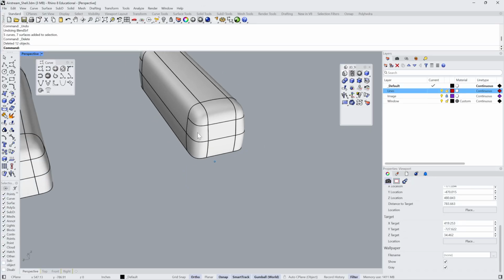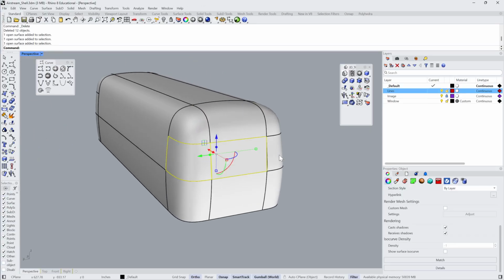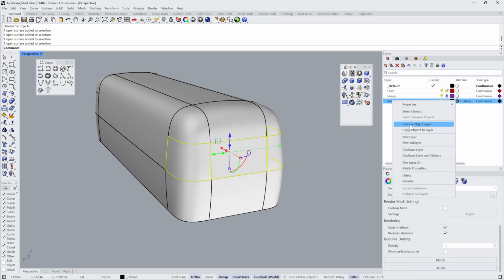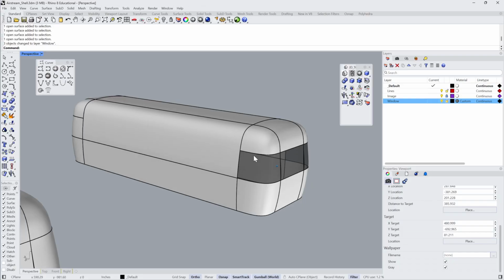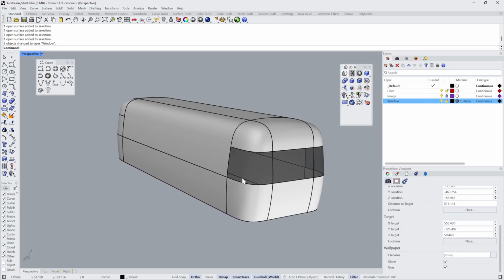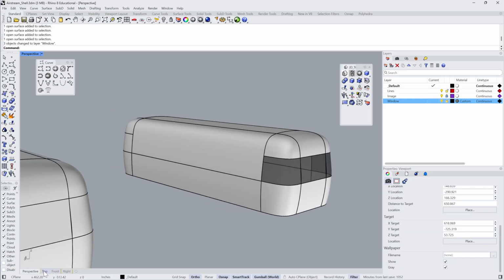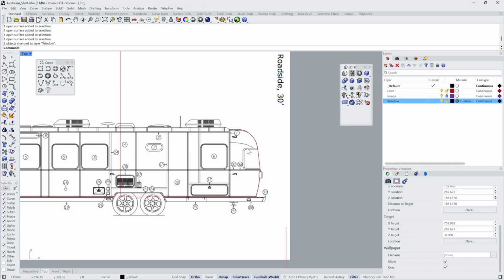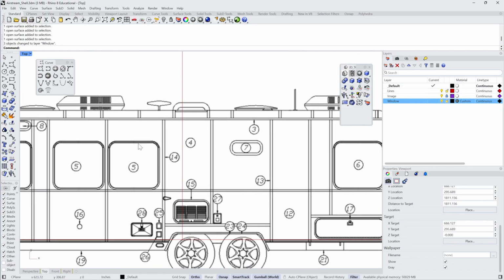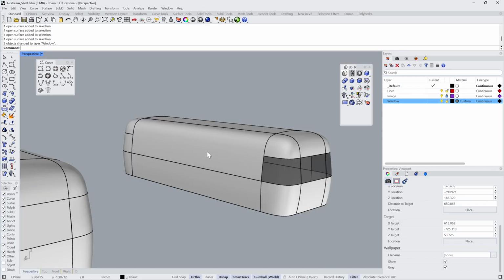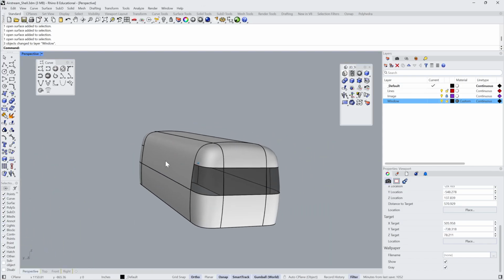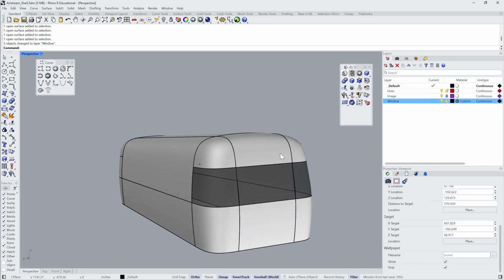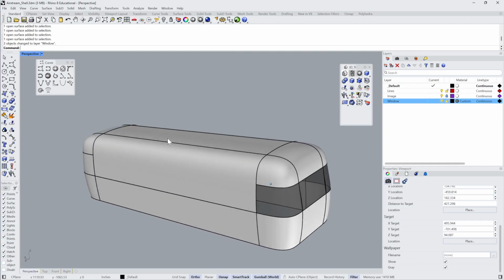Okay. All right, and then even though these windshields aren't perfect, we would want to come back and actually project curves, because we can see from our windows that these don't go all the way around and are filleted. But to get all of these windows, we would just tilt up this elevation. We would draw these windows, tilt up the elevation, use project curve to project them onto this, or extrude them through and slice out our windows. So that should be pretty familiar to all of you.